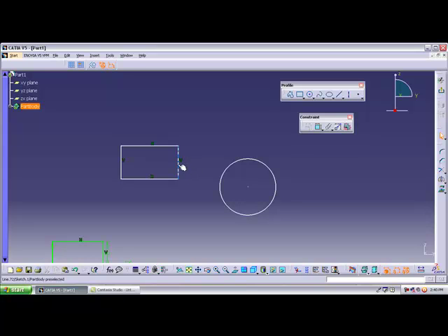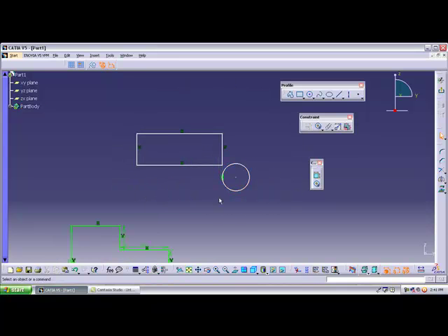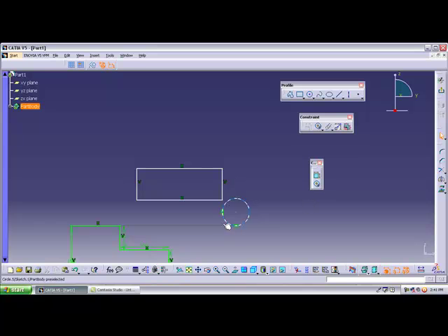Okay, select the line and select the circle, and in the geometric dimensional constraints, we click the submenu, and then you will get one more constraint. It is called the contact constraint. Right now this line and the circle are in contact. How is it in contact? By the property of tangency maybe. Suppose I want to contact this circle and this line, it is possible by the contact property also. So this is called a contact.